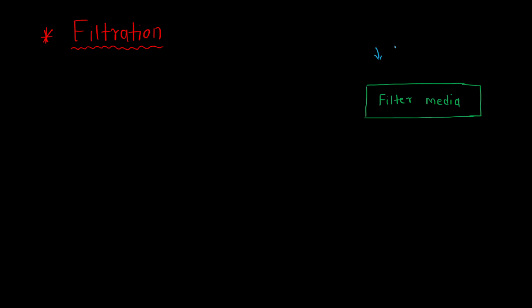When the water is passed through this, so this is water, when the water passes through this filter media, the impurities which are present in water, basically some microorganisms, colloidal particles, and also dissolved particles, get removed by the filtering action, and the resultant water that we get after filtration is pure water.